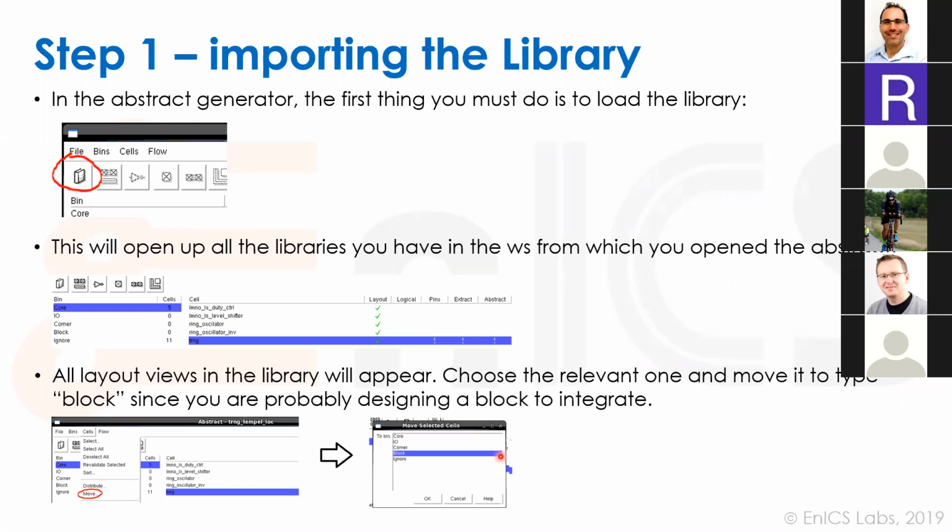Slava, I haven't dealt with it for a while, but you probably can elaborate on that. I guess you are right about the routing, but for sure there is an effect on placement, because blocks have different placement constraints rather than core cells. Core cells must be aligned to the core site, which is the minimum standard cell existing in the library, which has some standard cell row height and some minimal width.